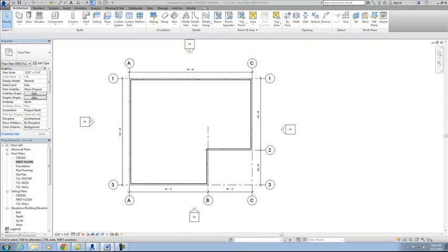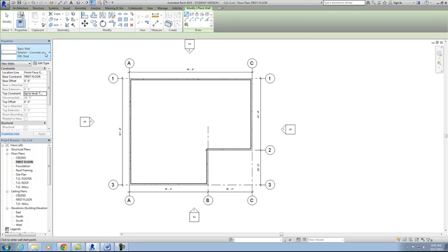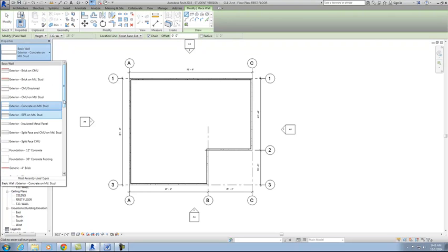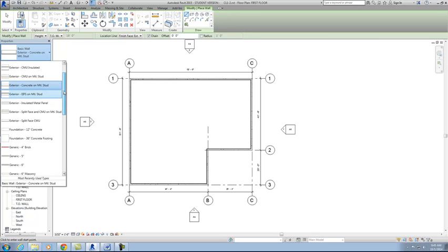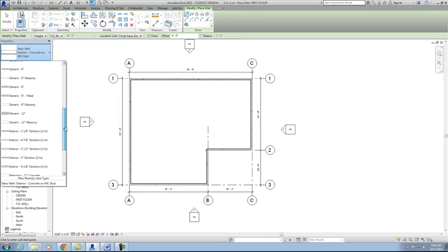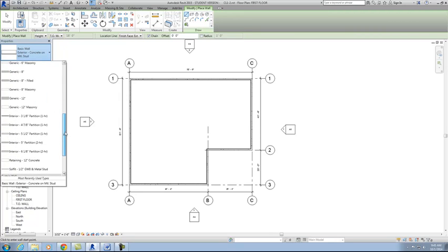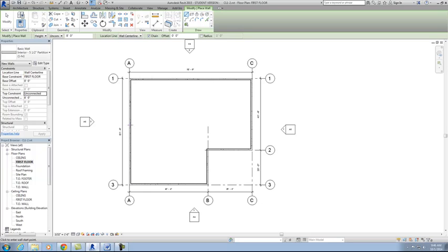Let's go ahead and add in the interior walls. So we're going to use the basic wall interior partition wall type. So let's go to wall once again. And this should already be preloaded. So we'll go down to, or up rather, I'm sorry, down. And we're looking for the interior wall. And we're using 5.5 partition 1 hour. The 1 hour just means the fire resistive level.